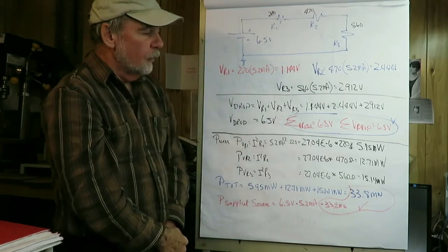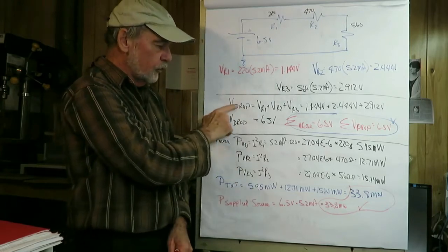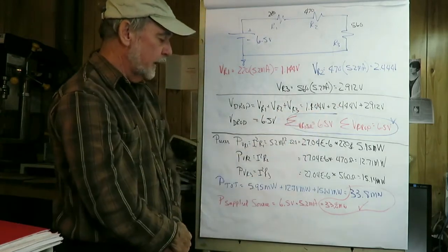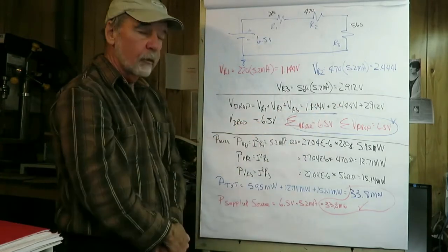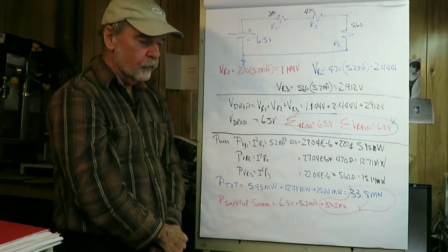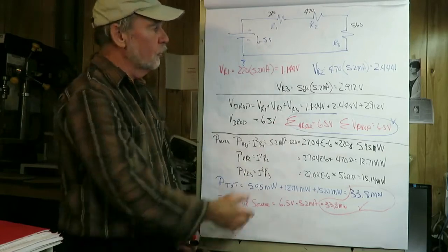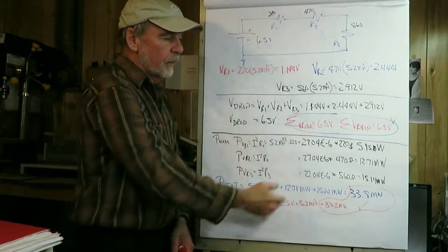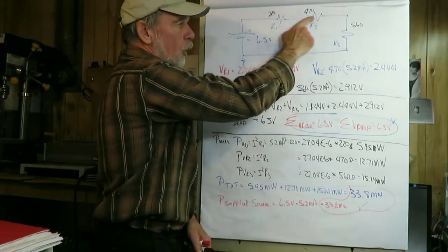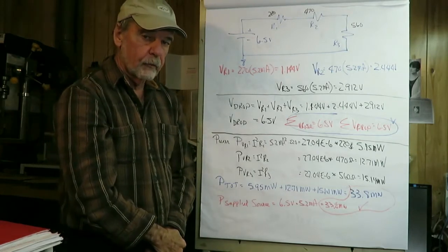So let's do a little check on Kirchhoff's voltage law. Let's add up the sum of the drops here. That would be these guys, and what that comes out to be is 6.5 volts. Notice that the source is 6.5 volts. So the sum of the rises, and we only have one source in this, 6.5 volts, is equal to the sum of the drops. That would be the sum of all the voltage drops across the resistors is also 6.5 volts.